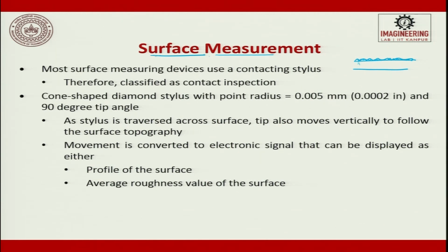Whereas in CMM, generally we used to take a lot of point data, and this point cloud data would be converted into surfaces. That is the difference between CMM data and surface data. In the latest advancement, CMMs have also started taking continuous data. So, today's CMM machines, whatever comes into the market, can also be used for surface measurements.